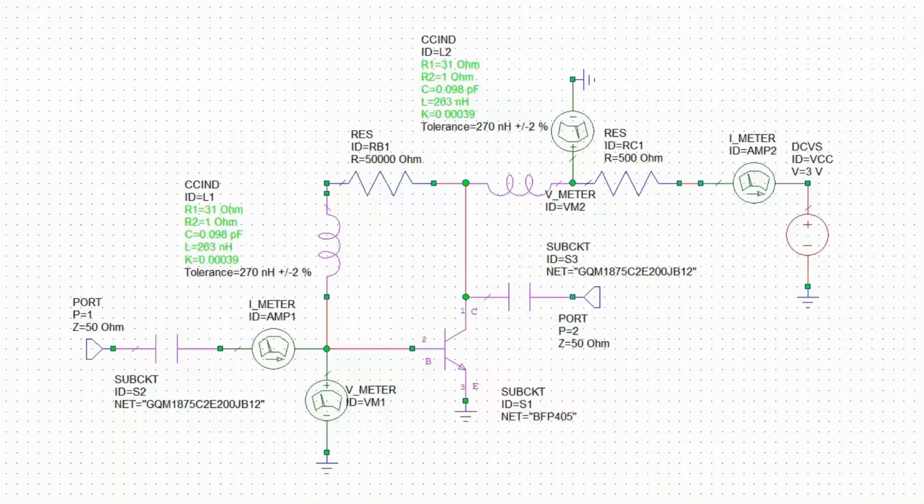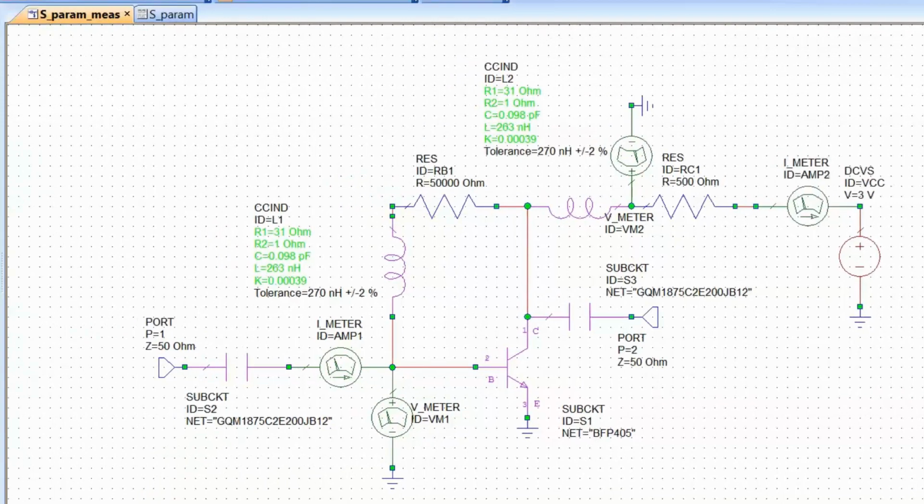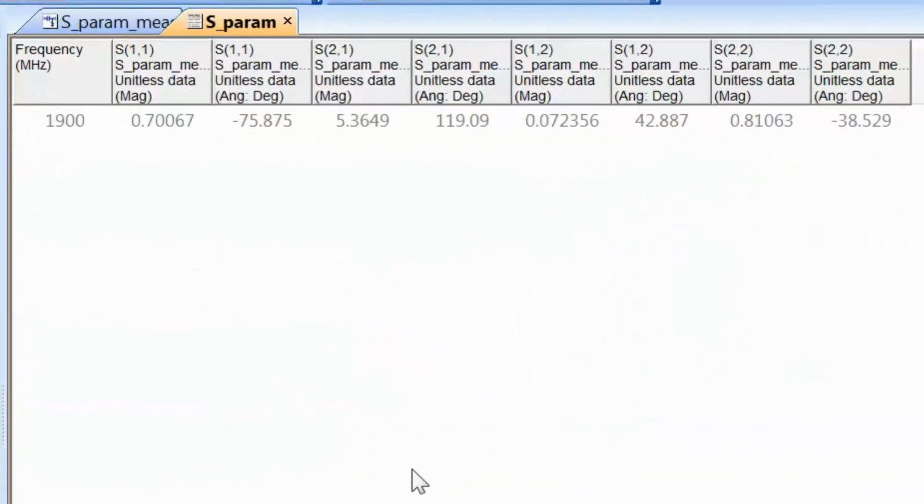GHz. We also looked at how to avoid high-frequency signals flowing back into our bias network and eventually into our power supply, which would then modulate the collector bias and cause potential instability, inefficiency, and potentially exacerbating nonlinearities of our active device. Once all this was done, we were then able to measure the S parameters for our transistor, and now we can use these S parameters to carry out the amplifier design.